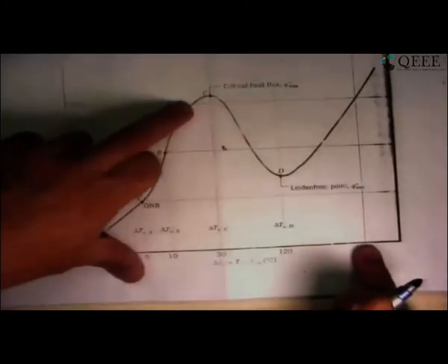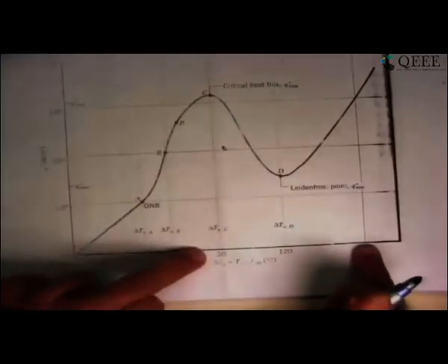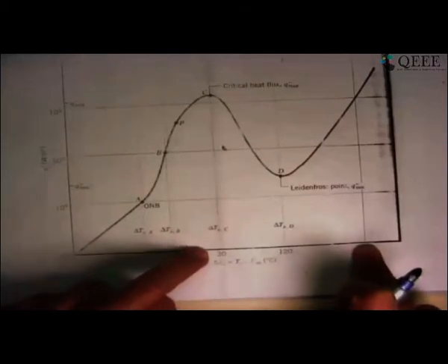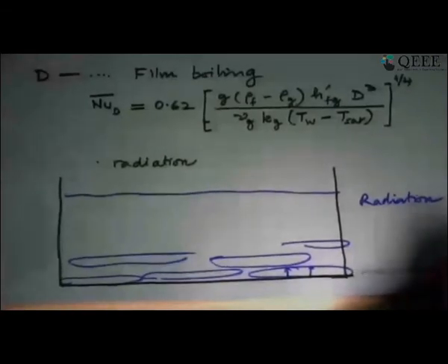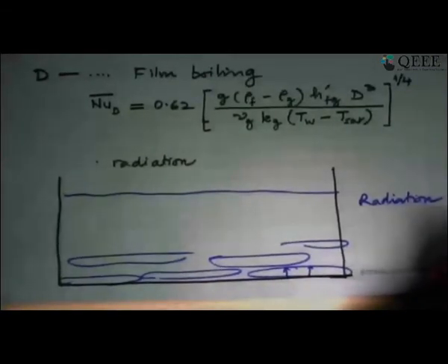So what you are seeing here is that you do get similar types of heat fluxes with a 1000 degrees Celsius temperature difference, but in this case you got similar heat flux at only about say 25-28 degrees Celsius. And that was here you had nucleate boiling, that was very nice for us. Here you got film boiling, which was not such a nice thing. Okay, so this is what is happening in this curve, and this whole curve is called the boiling curve. Relations are available for all these. You can pick up from the book, or I will pass it on in the notes. This is all taken from published research papers.